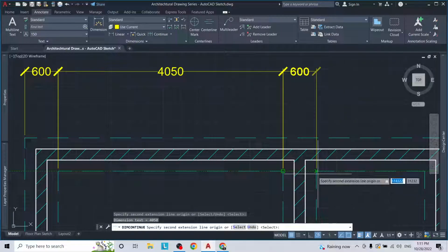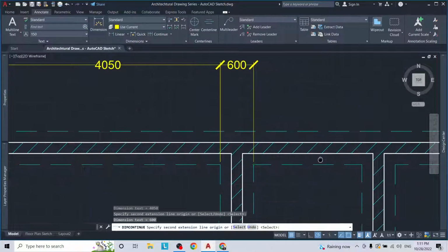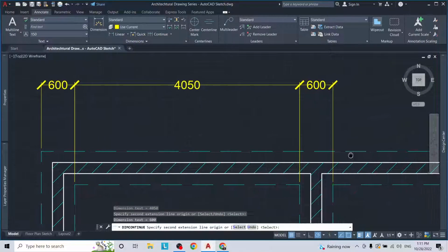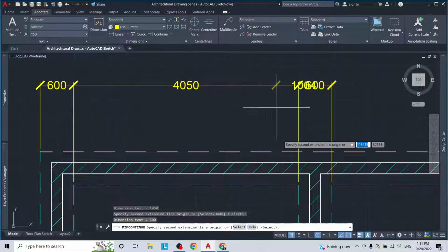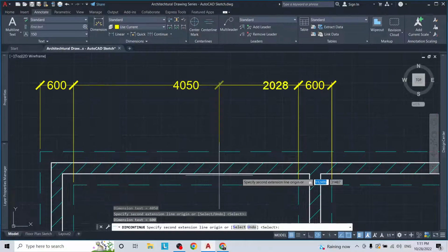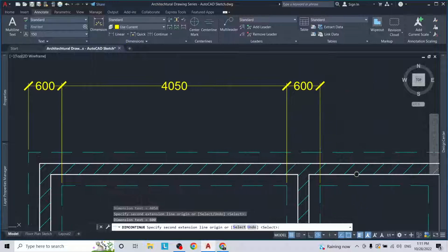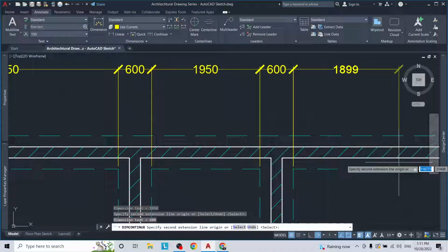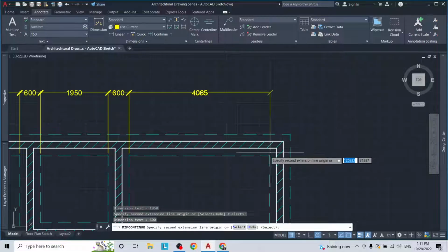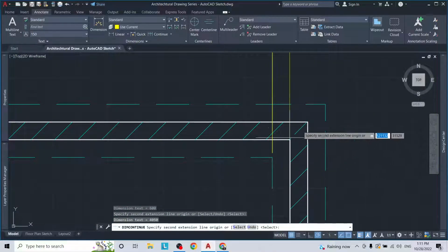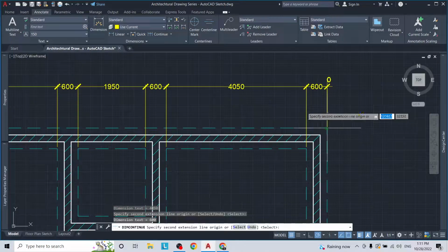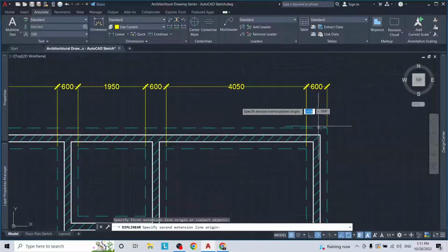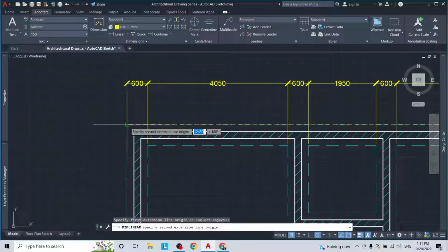So when they are laying out the building, they're going to be like, okay, so this footing is going here, and then the next one is going to go 4050 millimeters away from the first one, and that's going to give them all the information that they need to lay out the building properly on the land. So that's one there, and then the final one here, and after that, we're just going to do an overall distance like so, beyond it.